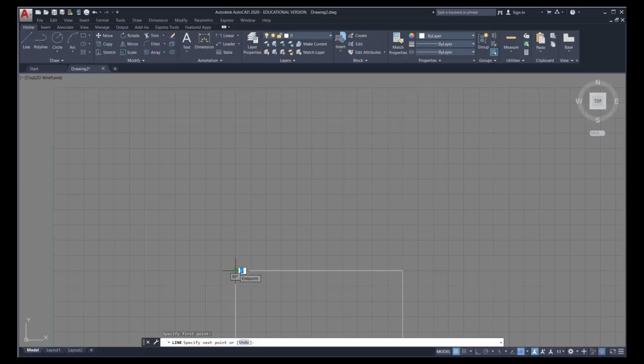I'm going to create a line that goes an inch to the left. So I'll type in -1, 0. And this particular line goes 2 inches straight up. So I'll type in 0, 2. And the next segment goes 2 inches up and 6.5 inches to the right. So I'll type in 6.5. Now for a 1/2 inch, I can use the 0.5 or decimal value, and that's a simpler way of typing in fraction inches. So 6.5, 2.